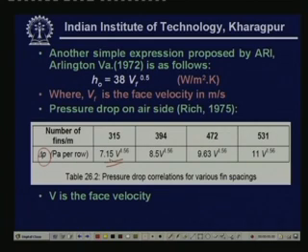So, this is equal to 7.15 V to the power of 1.56 if the number of fins is 315 per meter. Similarly, this is the expression for 394 fins per meter, 472 fins per meter, and 531 fins per meter, and here again V is the phase velocity. So, this is again a simple empirical correlation based on experimental observations.